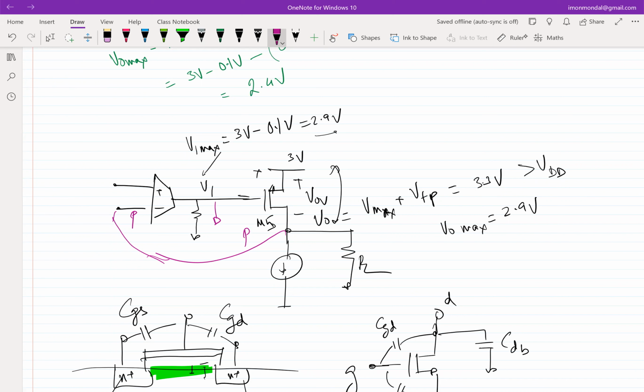So there is an inversion that has happened because you have put this common source. This is essentially a common source stage, right? The second stage is the common source stage with the PMOS input. Because you have a second common source stage, you have inversion. So naturally, if minus is not the terminal, plus becomes the terminal.